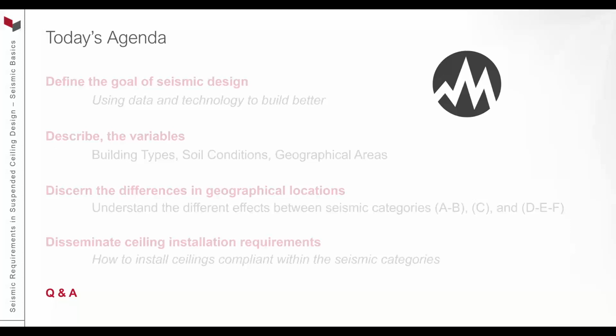So also from category D, do we always have to use perimeter wires? Perimeter wires are required for ASTM on every cross-tier main tee. But in some situations, and it's kind of funny that it came from OSHPD, or the Hospital Designers, now HCAI, where they're building and designing hospitals. In hospitals, if the perimeter tile or the perimeter cross tee is less than 8 inches, then we do not have to put a perimeter wire on that ceiling.